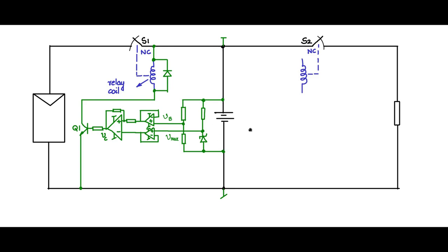Now coming to the other portion of the circuit, let me connect a resistance and a Zener. This resistance and Zener is used for determining the other reference voltage, which is Vmin. So I will buffer that also and pass it to the comparator. I will have the op amps powered by the battery supply. I will have another buffer. I don't need this buffer actually, but I am just showing it for completeness.